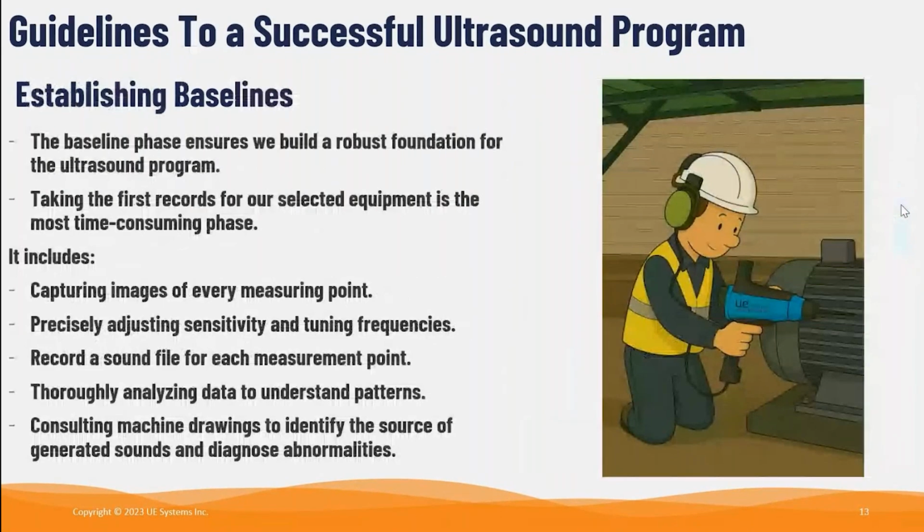Once the database is established, we will be ready to collect our baseline measurements. This phase typically is the most time-consuming phase, as we capture images for each measuring point, adjust the sensitivity and tune the frequency for each point, record sound files, analyze the measurements, and learn more about the unique ultrasound patterns for each piece of equipment. Although this phase requires a significant time investment, this phase is the most important. It builds the essential foundation for all future measurements and analysis.